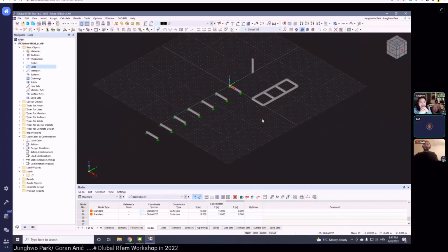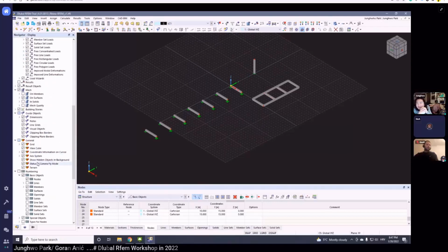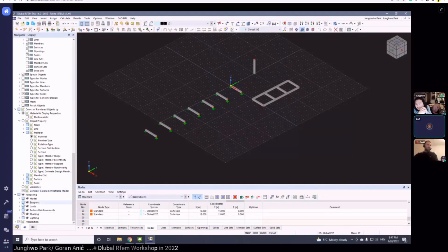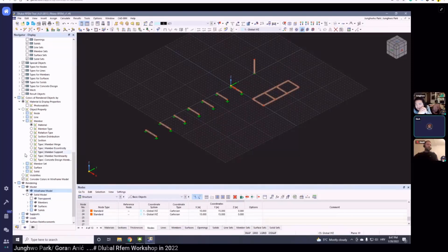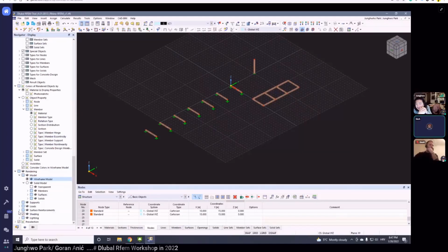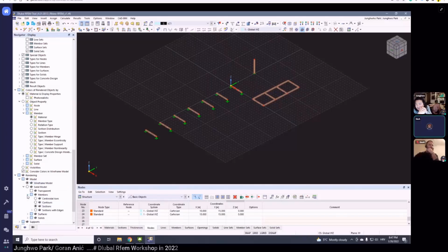Can you also display only lines instead of the solid model? Sure, visibility. Just a second. Let's see, member, rendering model, solid wireframe model, and I should turn off this presentation of reinforcement, surface. Where is this? Members.